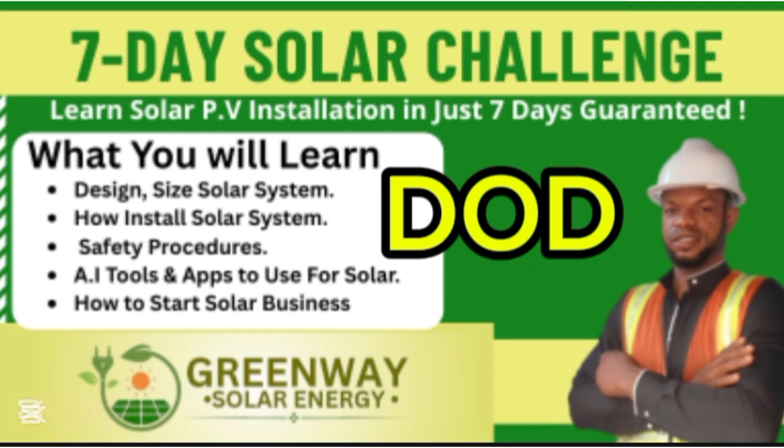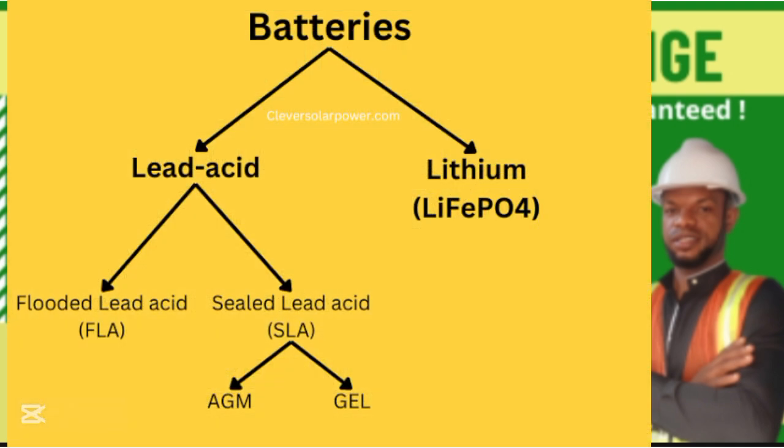These are the battery types and their typical safe zone of depth of discharge. Lead acid battery is at 50% maximum. Lithium ion batteries, depending on the make and the type, some have 80%. But let's say that lithium ion batteries have a safe zone of depth of discharge within 80 to 95%.